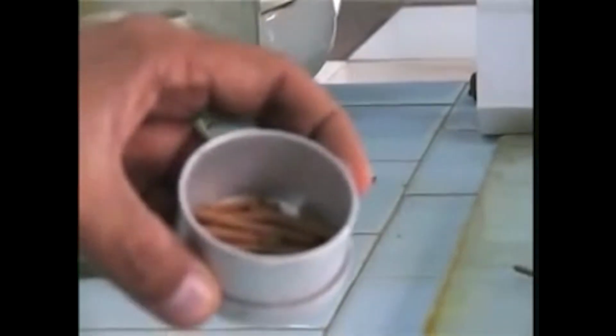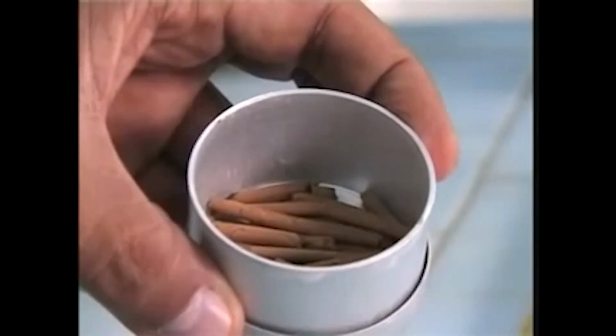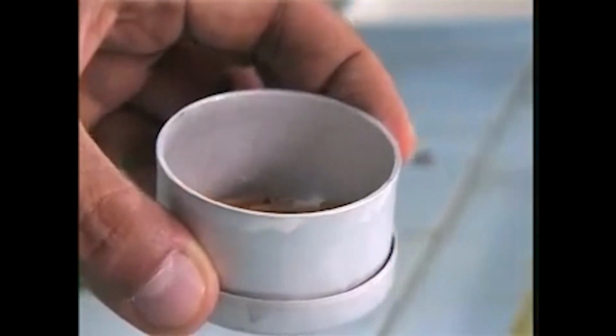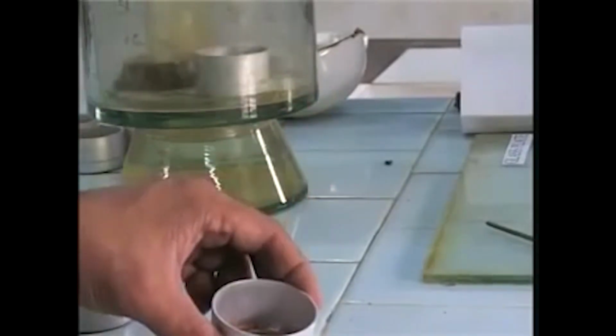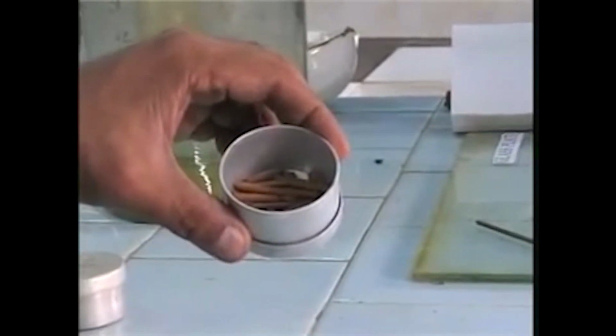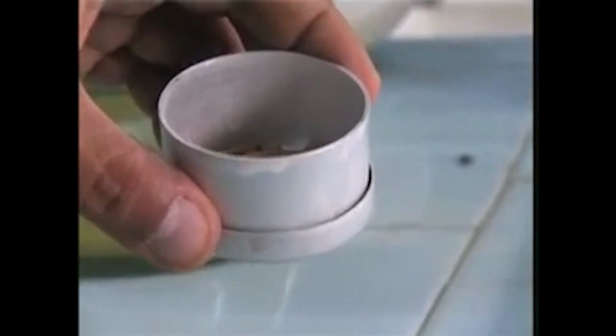So we are going to save enough of such sample in moisture content pans like this one, and we are going to find out a representative value of moisture content from a large amount of soil by rolling several different threads, because that is going to allow us to minimize the amount of error in the experiment.